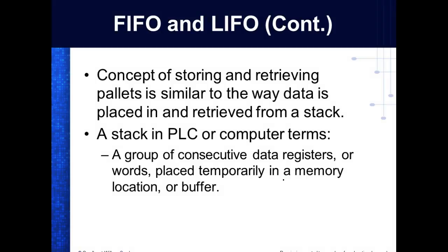The concept of storing and retrieving pallets is a stack. In PLC or computer terms, a stack is a group of consecutive data registers or storage locations or words placed temporarily in a memory location or a buffer, a go-between. So it's consecutive addressing. By the way, you can access the stack with any addressing. It's just that if we use the stack instructions, they're going to be put on there sequentially and pulled off sequentially. Make sense? But it's got an address.